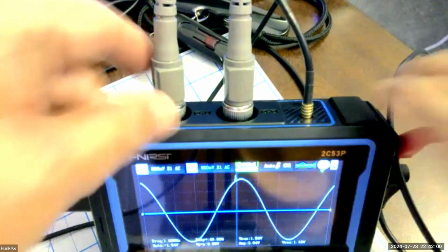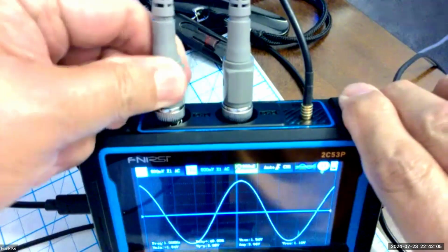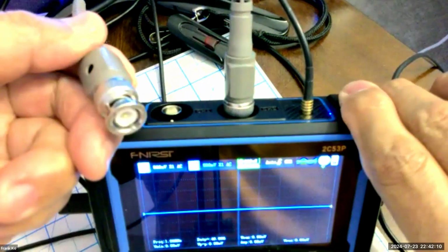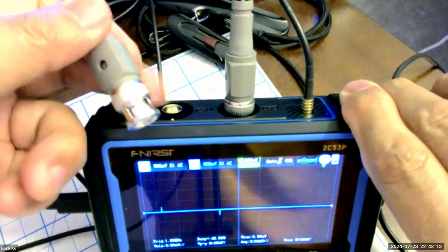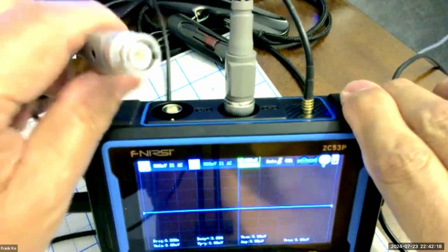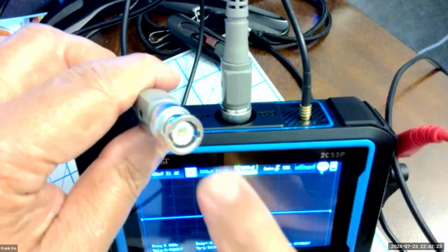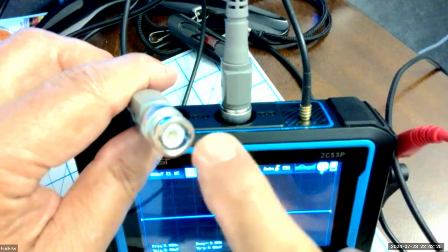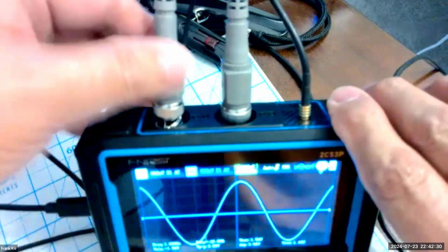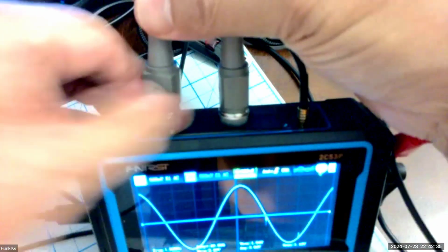And so this particular guy, we'll just do this for a moment, untwist first, and then lift this up, and it comes out. There's the business end of the BNC, and there's the receptacle of the BNC, and there's two pins that have to fit into the two slots. Right there, you can see a slot there at 3 o'clock and a slot there at 9 o'clock. They fit on pins, so you've got to look at this very carefully when you line it up. And then it's spring loaded, so you have to push down. And while you're pushing down, you rotate this collar